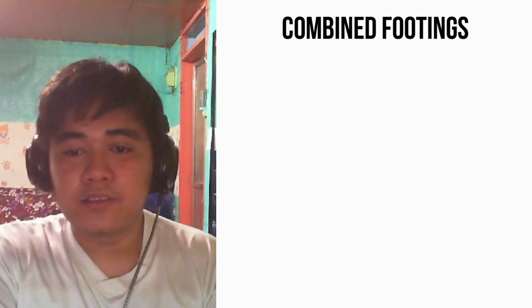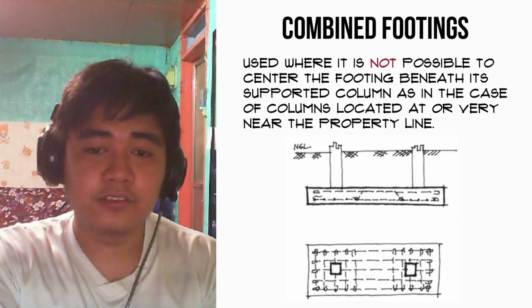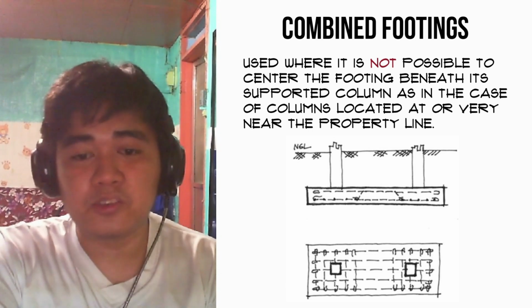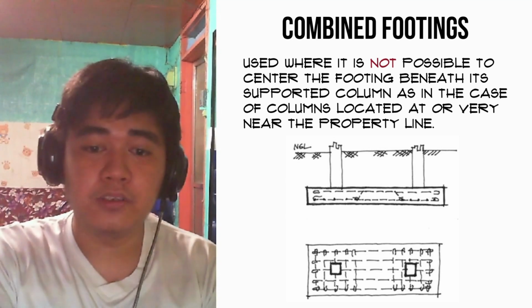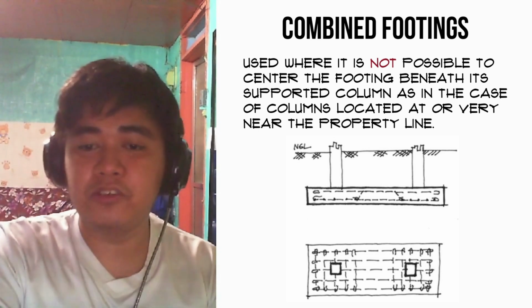Combined footings can support two or more columns. This type of footing is used where it is not possible to center the footing beneath its supporting column, as in the case of columns located at or very near the property line. Combined column footings are usually rectangular and trapezoidal in shape.